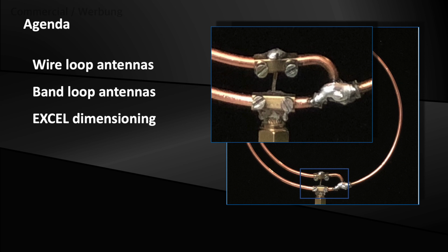The antennas shown here are intended for frequencies from 100 MHz to 5 GHz, which corresponds to an antenna diameter of around 2 centimeters to 1 meter. What I particularly appreciate about these antennas is that they are a bandpass filter and an antenna at the same time.